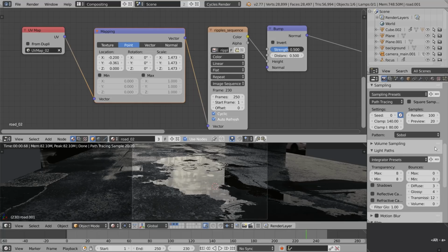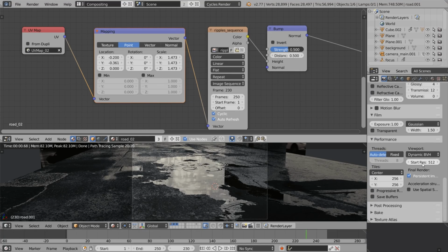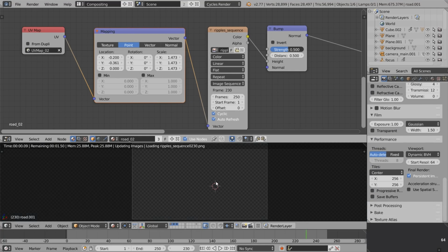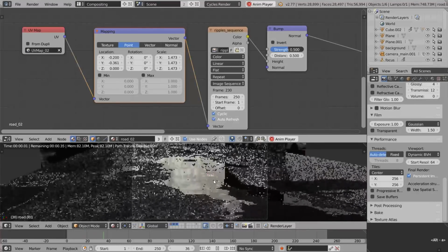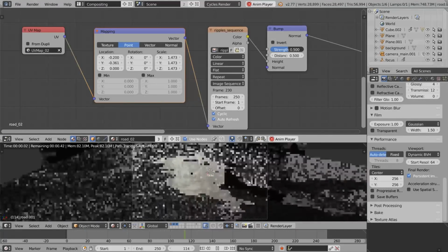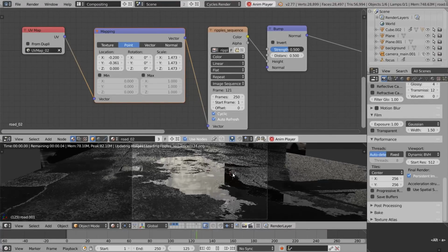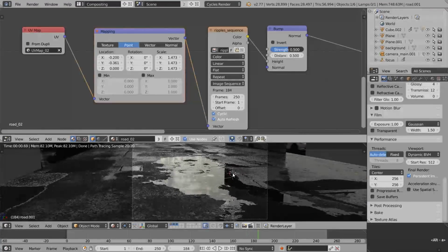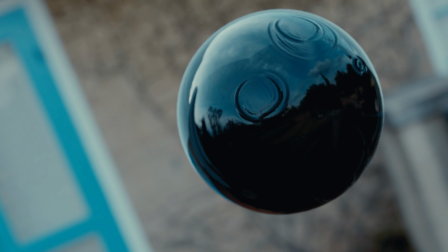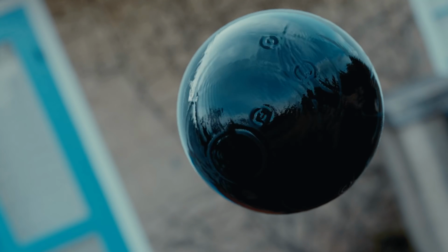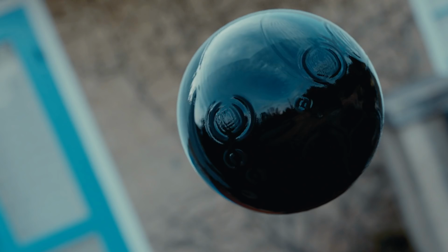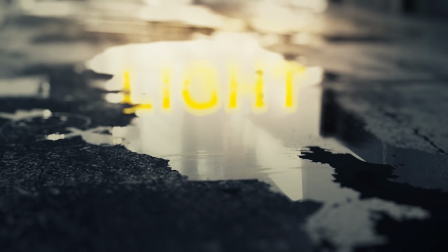One more trick for you so you can easily preview it in the viewport. By default, the start resolution is set to 64, and that means that the preview is very noisy when you press Alt-A. I'm usually setting it to 512, and it provides a very smooth viewport. And as I've said earlier, you can use this effect in very creative ways, like for making the ripples, or maybe a ripple in water.